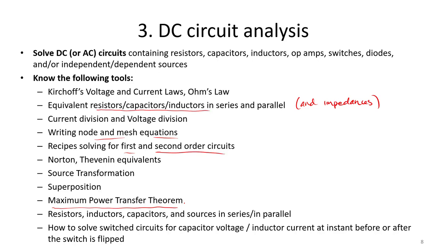Also, make sure you understand how to simplify switched circuits. Remember when we have switched circuits and we want to calculate capacitor voltage or inductor current at the instant before or the instant after a switch is flipped? And definitely being able to simplify series and parallel inductors, capacitors, resistors, and sources.